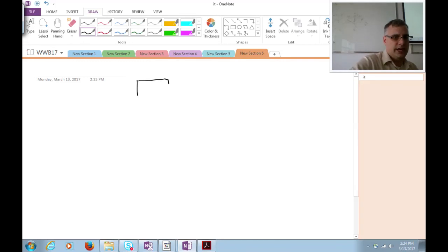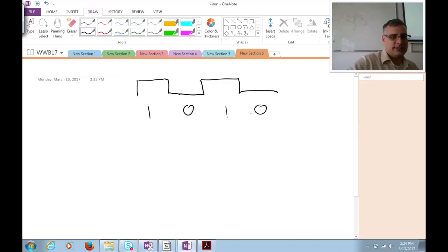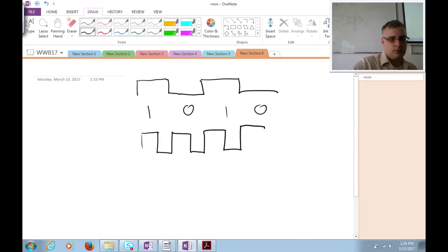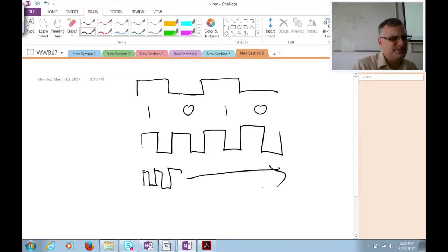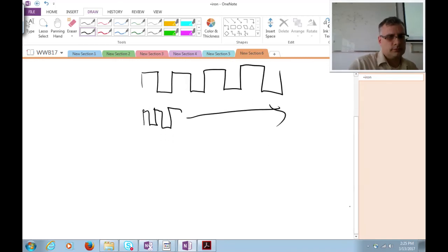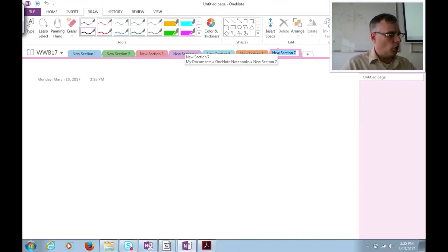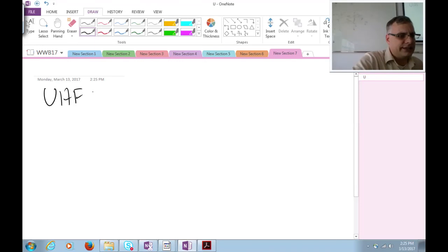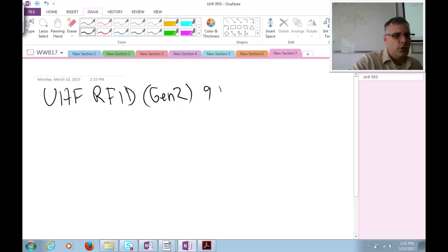One way to view F2F is that you're taking a data sequence, and then you're multiplying it by a square wave, and then another higher frequency square wave on top of that. So one way to help balance the signal on a UHF RFID tag, and here I'm talking about the Gen 2 standard, the one for 915 megahertz that almost everybody uses now,